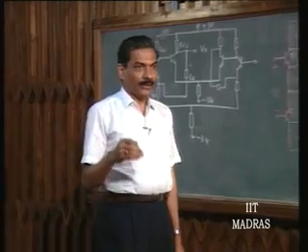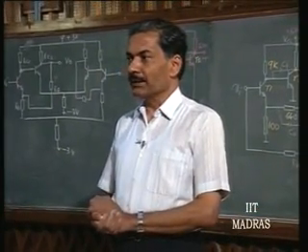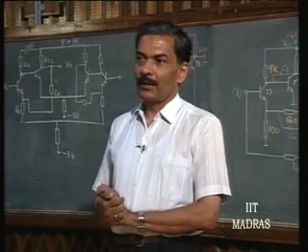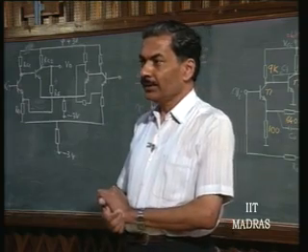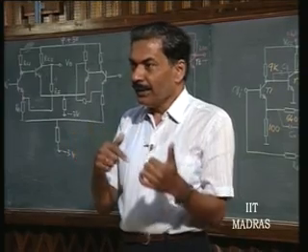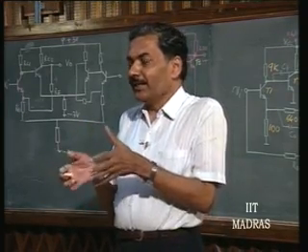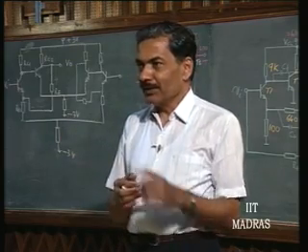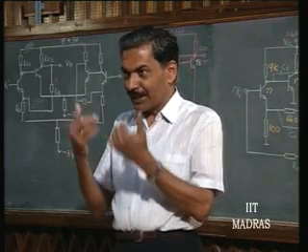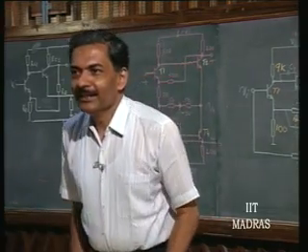Now, to prevent oscillation here, what is adopted is not dominant pole compensation, it is pole zero compensation. That is, I will introduce a 0 to cancel out one of the 3 poles, so that it becomes a second order system. But in the process of doing it using a capacitor, I cannot but introduce another pole.